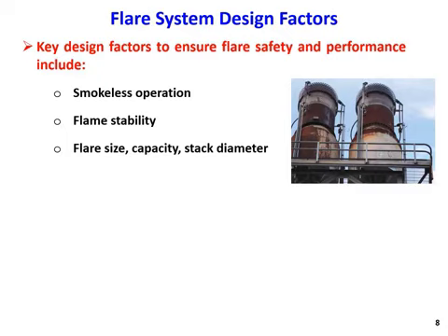Flare size, capacity, stack height, so how much gas in the worst scenario the flare is receiving. This is the flare capacity, how much gas the flare has to burn in the worst scenario. If we calculate this when we are designing the process, then we can calculate the size of the flaring system, I mean the diameter and the height. All of this can be designed properly based on the capacity if it's known.